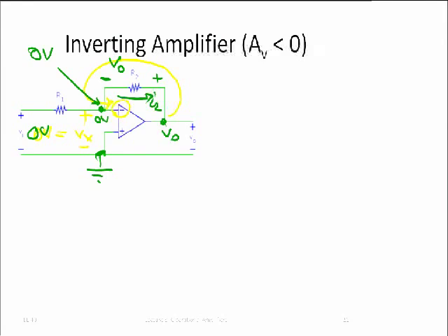Okay, all right. So let's see, what do we know? Well, we know Vi, of course, right? We want to know what Vout is for a given Vi. We know R1. Well, do we know the voltage across the resistor R1? That's Vi. Well, do we know the current I1 flowing through the resistor R1? Well, of course, we know that. It's equal to Vi over R1.